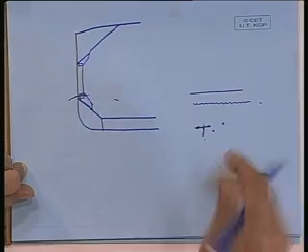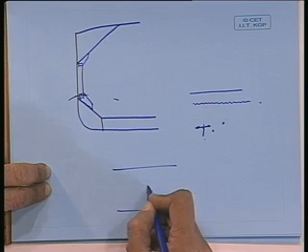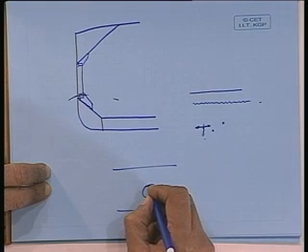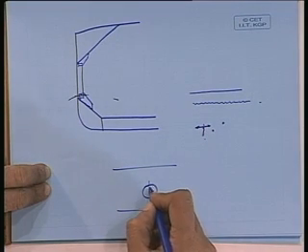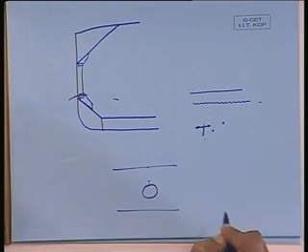The shipping classification societies consortium has done a combined research and come to a conclusion like this. But a stage comes when this keeps on propagating, and once again when it opens, you will find that the surface, if I just try to elaborate it here, say the crack has opened this much. That means this cross section is still intact to take the load.